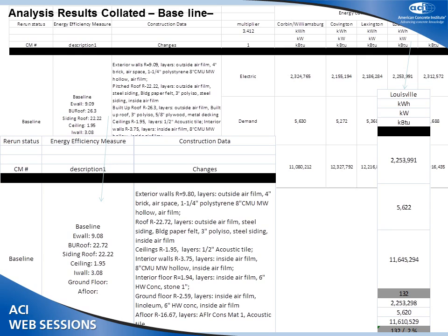What we did then is look at the annual energy use, if you'll see down in here, for each of the different cities, using Louisville down in here, for electrical energy use. In our base system we used a boiler system for heating and a chiller, basic DX unit for the cooling on the system. We used standardized schedules for the classroom space occupancy, etc.